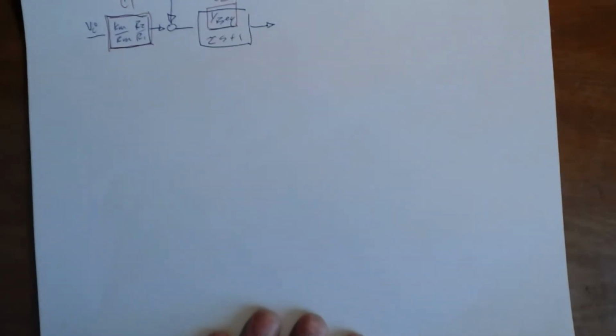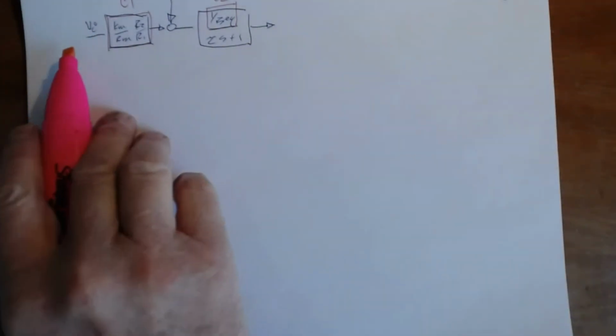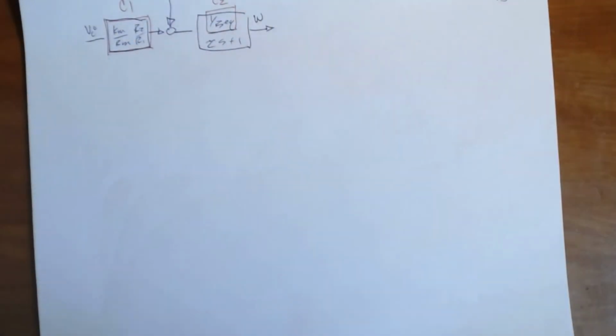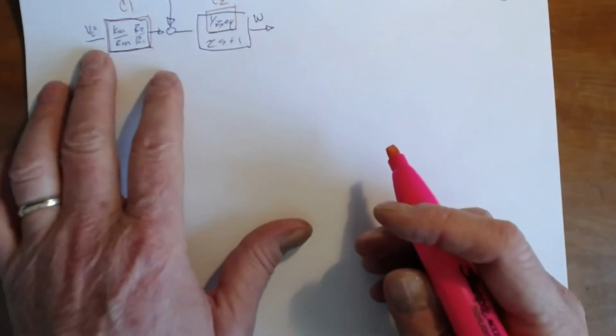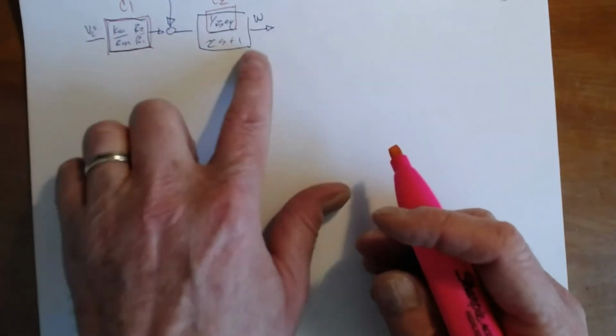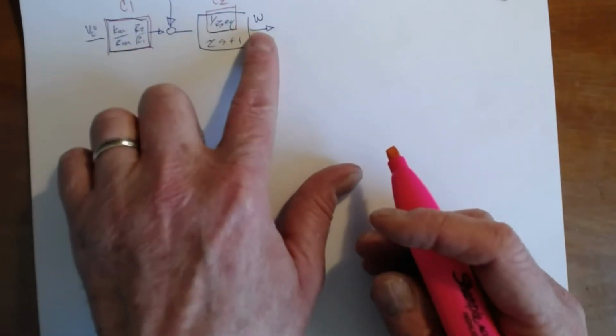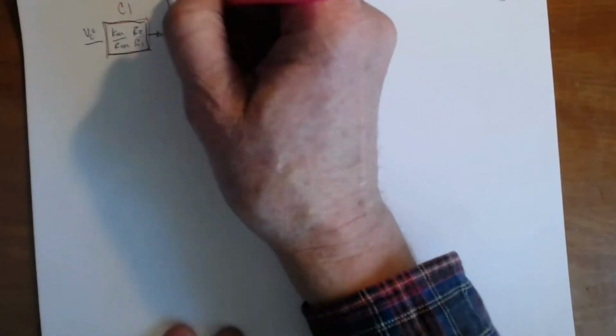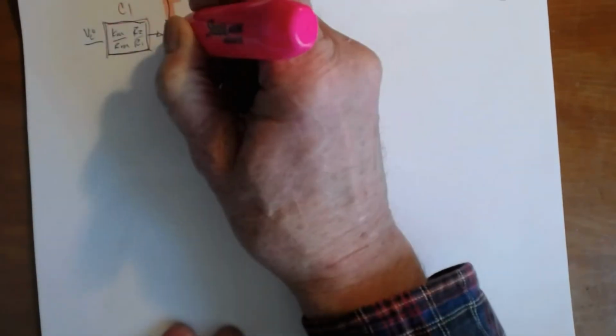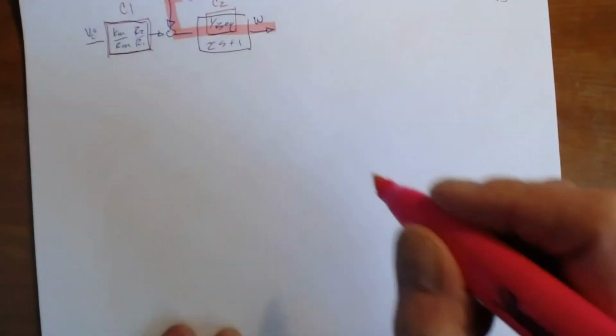In the open loop system, what I'm going to try and emphasize to you is that it doesn't have anything to do with Vn anymore. So now I've got my motor going at the right speed, omega. I've calculated the perfect voltage to make this thing go at the perfect speed. But now somebody grabs a hold of the motor shaft, and this is what the open loop system looks like.